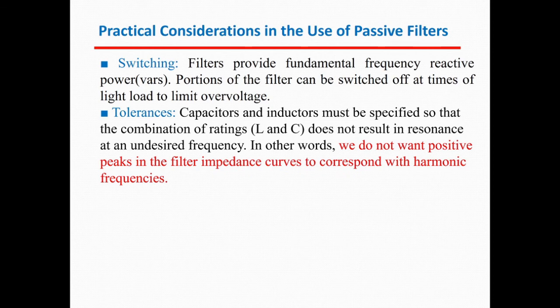Tolerances. Capacitor and inductor must be specified so that the combination of ratings does not result in resonance at an undesired frequency. In other words, we don't want a positive peak in the filter impedance curve to correspond with the harmonic frequency.